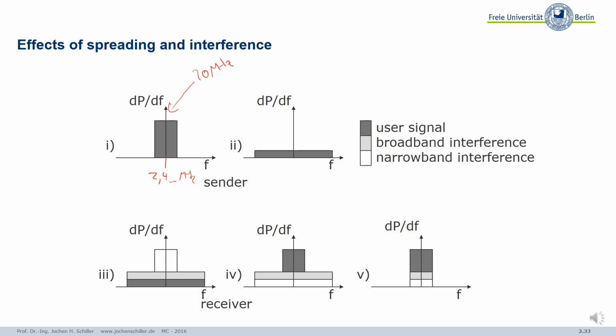So what you do now is you can spread this. How? I will explain. Basically, instead of sending, let's say, 10 megabit per second, you can send 1 giga symbols, chips as we call them, per second, spreading your signal. What happens? All the energy you have here in narrowband is now put into this wideband signal.